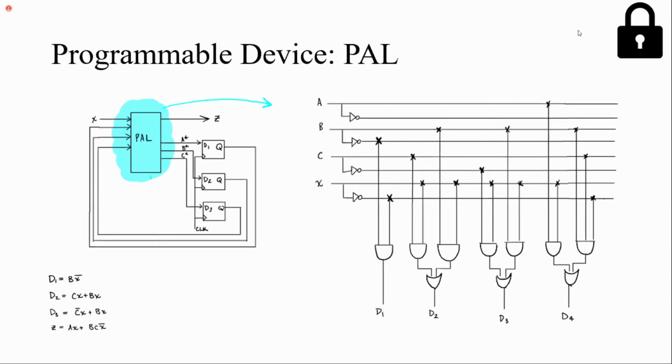So here is my drawing. I just wanted to draw to see how it would look. Because Multisim and Logisim don't offer actual PALs to use, I ended up just drawing the hardware inside of a PAL to show how it works. And I used D flip-flops to do this. I ended up using this design because I believe it was the simplest compared to using traditional ICs, because ICs are sometimes not available and they waste space on a circuit board. So I thought this would be the best condensed version of my project.